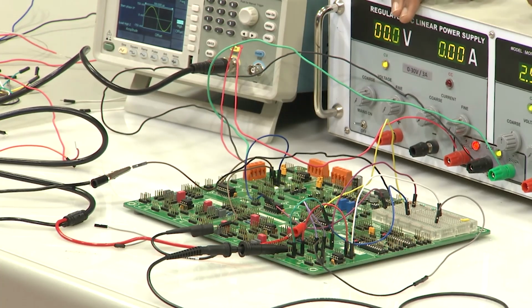So we have to select resistors. The resistors will have their tolerances. What we have selected here is a 2.2 K resistor and a 1 K resistor as R2 and R1, and we have connected it up, but because of small resistive fluctuations, we will get a reasonably similar gain. Theoretically the gain would be 2.2. We will see practically what gain we are getting, and more importantly, we will see what range of input gives an output that is not saturated, meaning the output does not get clipped off at the saturation voltage of around 13.5 volt.